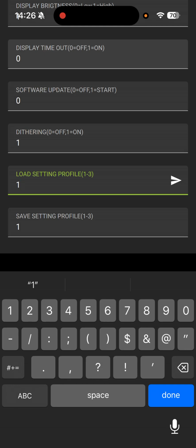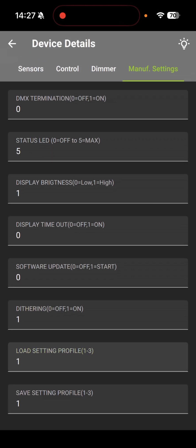Again, using the IllumaSync app is much faster because you can do multiple controllers at the same time, but this is a great way to update many controllers all at the same time without having to go around to them individually one at a time and set every single setting. So this saves a ton of time for commissioning a project. And also if you do have to do any kind of updates in between scenes. So that is the, I'm just going to save that.